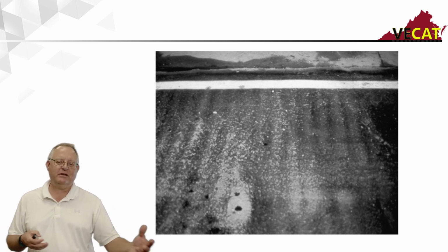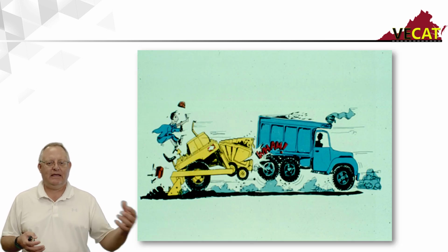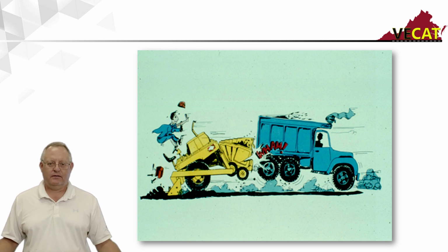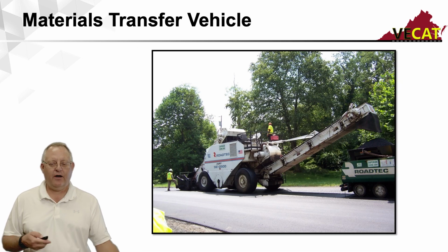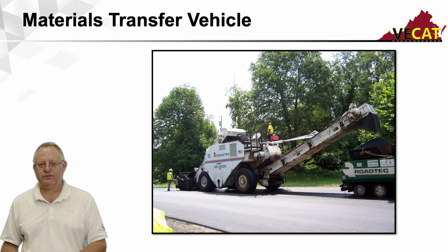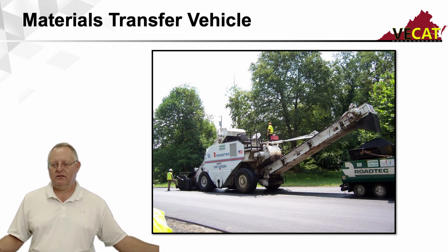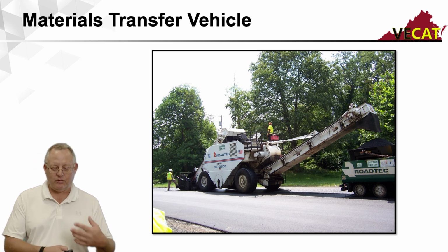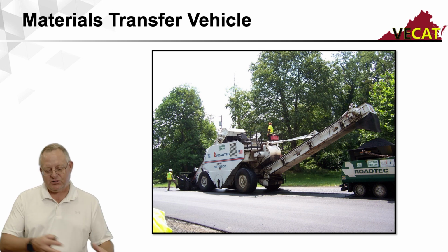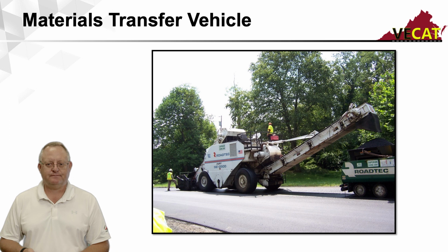Sometimes when we're paving and we don't have a transfer vehicle, that truck backs up into the paver, you hit it, it creates a bump. Now you can't get it out. We can overcome that by using transfer vehicles. That transfer vehicle separates the dump truck from the paver. It can go through the transfer vehicle, get remixed, make it uniform temperature, go all the way through, pave it through, end up with a much better mat.